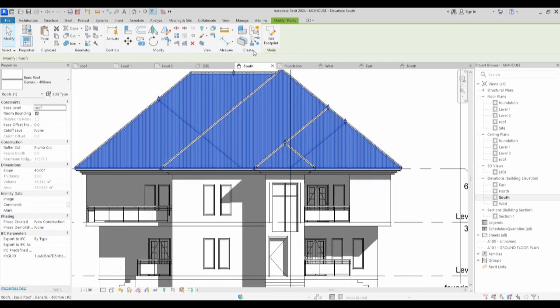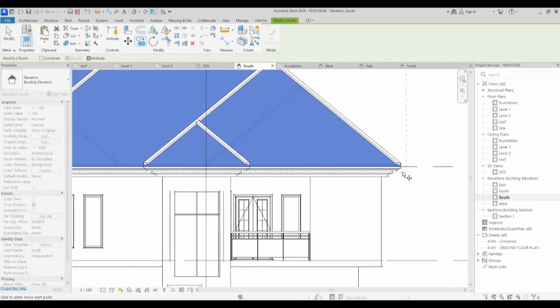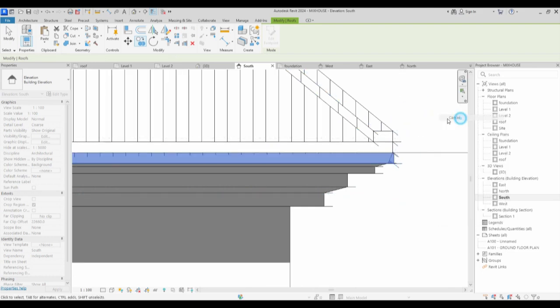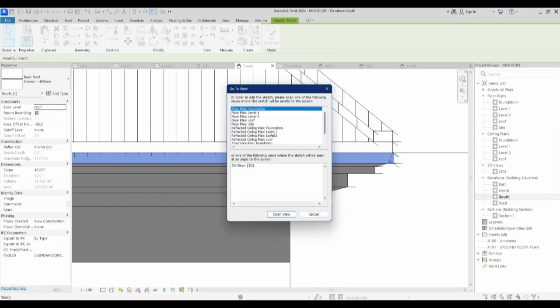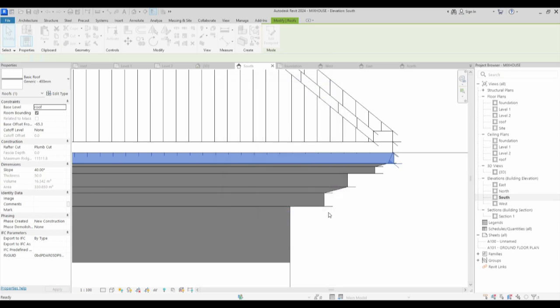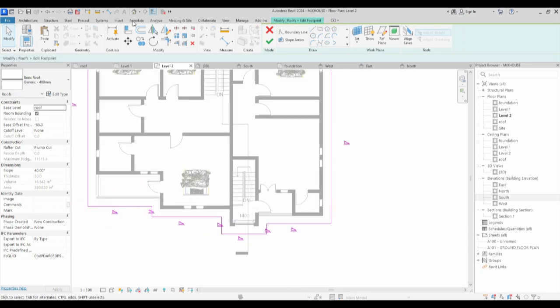So you copy this roof, paste it down here. So then you say edit in place, edit here again, or yes, just open that. Then you now offset this inside by 200, not 300, but 200. You should do okay without copy. So this one will move in.